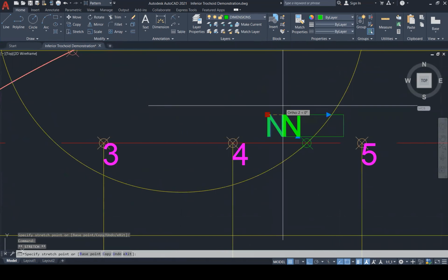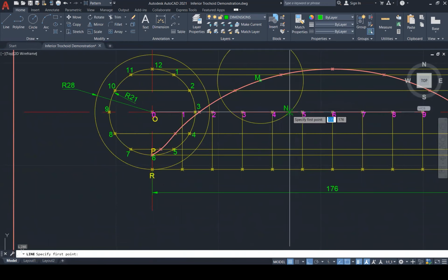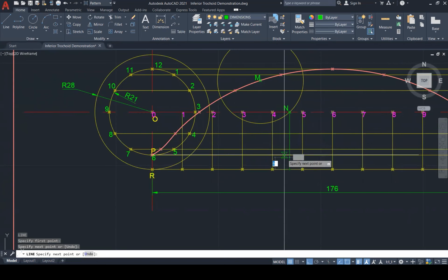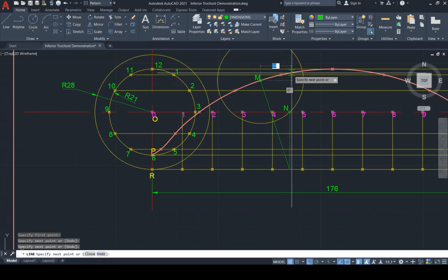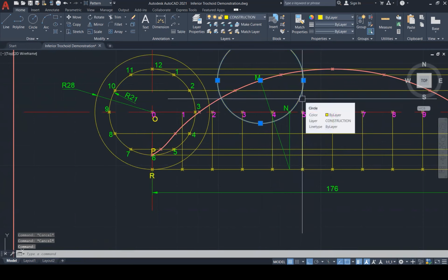So this is point N. And then at point N, what we do is we take a line and go straight down to the baseline and create a perpendicular, right? And from that perpendicular point, we then connect to M. That goes all the way back to M. So first, we locate where M is, where we want to put this point on the curve.